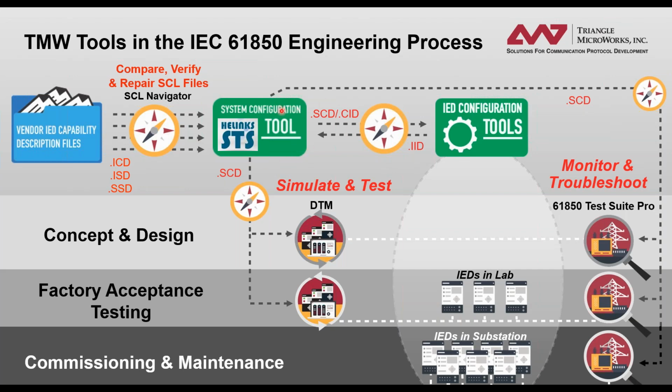Well, then when that system configuration file, the SCD, is produced, it is then consumed by the IED configuration tools for each of the different vendors. And this is a place where we can get into some troubles in the field. Unfortunately, there's sometimes disagreements in how the standard's interpreted, how SCL is consumed and produced. And so we see a lot of customers that have a lot of time and expense wasted in the field when the SCL file is transferred between two tools and the vendors disagree on some concept in the standard and how it's implemented, and that can cause a lot of wasted time.